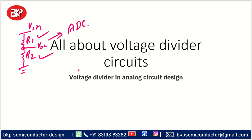So let us say we have an input voltage and our aim would be to identify R1 and R2 in such a manner that we can find out our Vx. Vx is the voltage which is going to go to the input of ADCs or comparators or somewhere. So our aim is to design R1 and R2 in such a manner that Vx is well below the reference voltage, right? You would have seen many of these circuits.